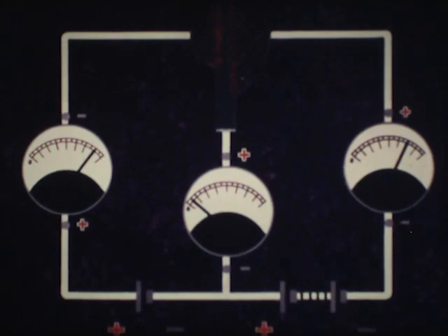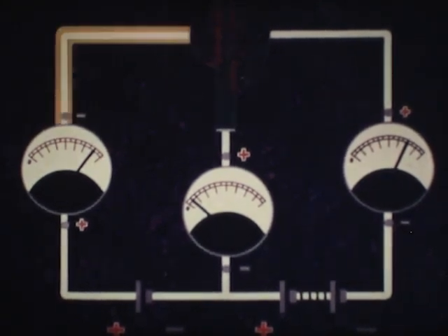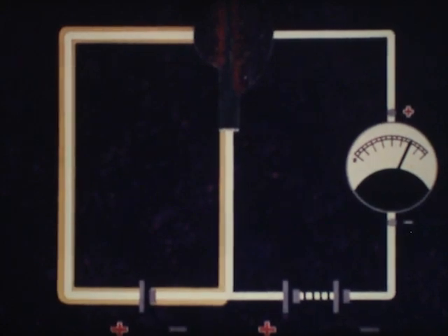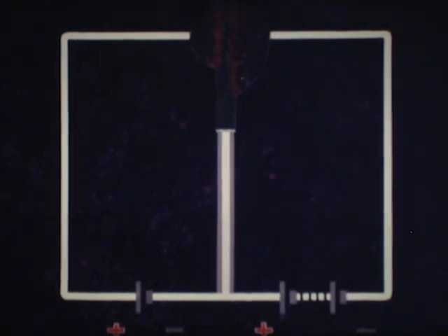In the transistor configuration shown, the emitter-base junction forms part of the input circuit, and the collector-base junction part of the output circuit. The base region is then common to both input and output circuits, hence the name common base configuration.